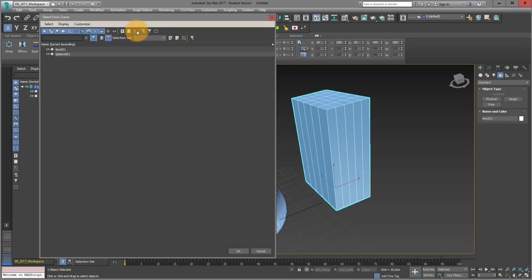And what I also quite often use is this kind of menu. If I have many, like hundreds of objects, then it's really difficult to navigate through the amount of objects. And if I want to look for one specific object and I know the name, I just enter B-O, and then, for example, you can only see the objects which start with a B or, for example, with a C, like sphere.